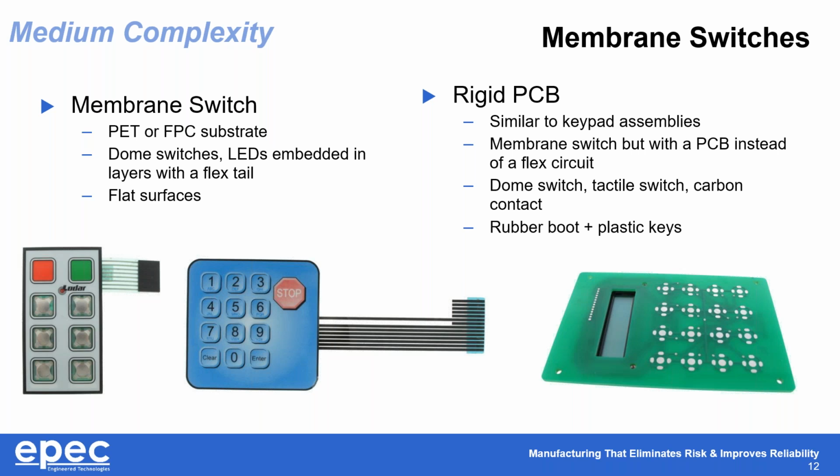With these types of switch technologies, the majority of them use either surface mounted tactile switches or these convex dome switches made of stainless steel. These are extremely high reliability and relatively simple technologies, but with some tricks and nuances to their assembly and test.